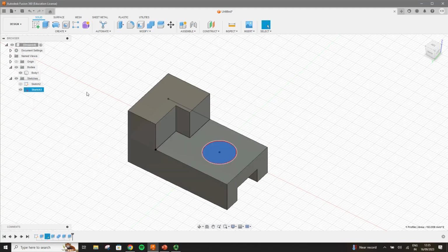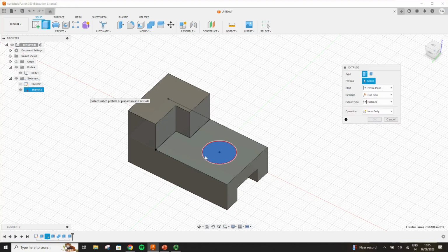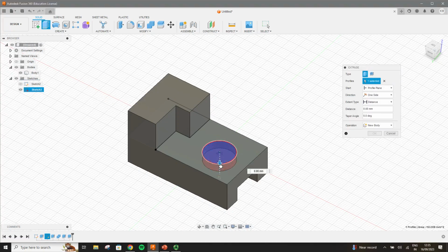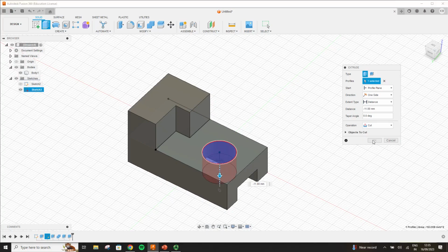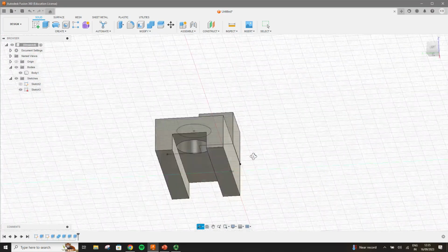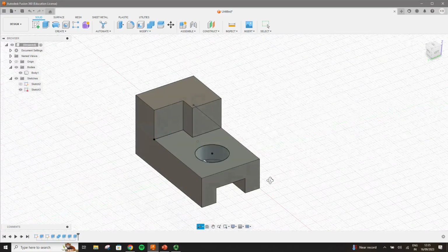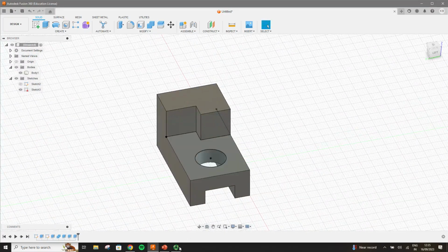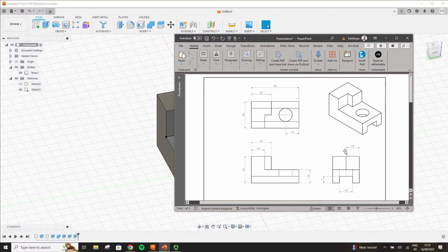We just have to make that hole, and it's very easy, we know that, right? So we can use extrude again and extrude it all the way through, and that is it essentially. If we press OK, you can see that while extruding, I didn't even give a dimension because I just pulled it, since I know that I want to go all the way through, so I can remove all the material under it.